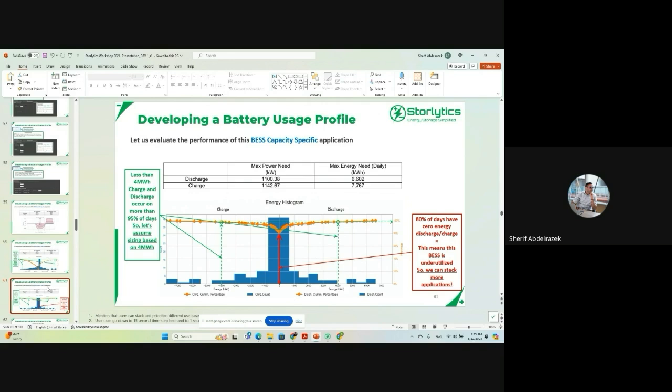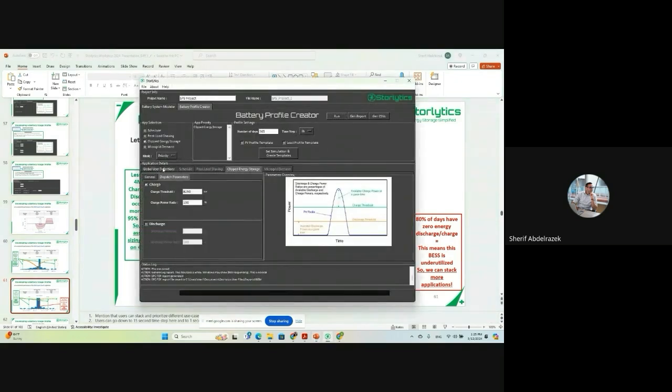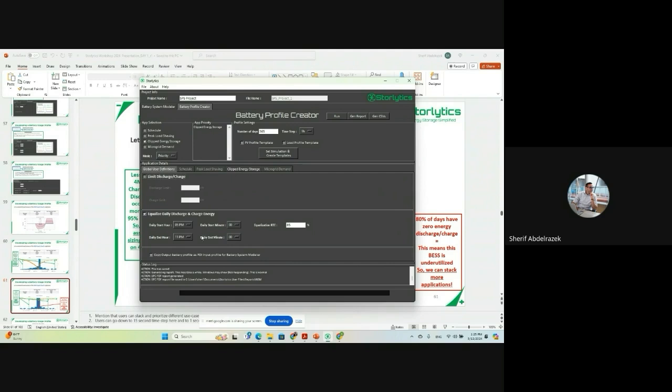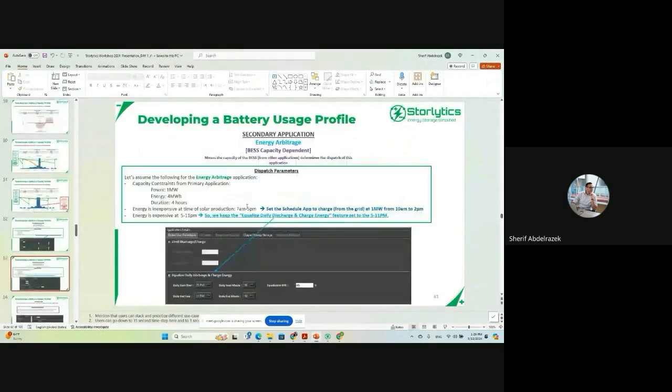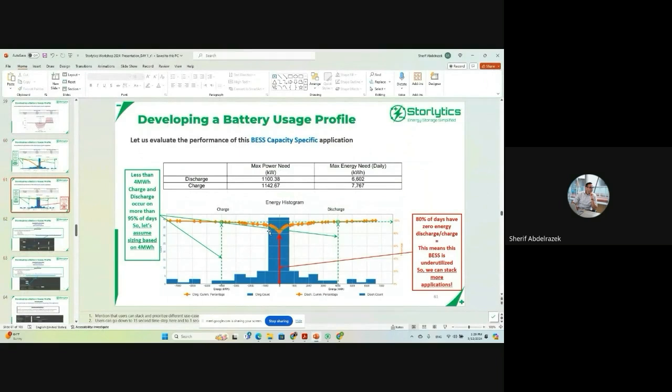For discharge, if discharging was calling for more power, I can maybe say, all right, how about I go back and increase the discharge period? That would reduce the amount of power I need. So as you're building your simulation and designing your project, you can prioritize different aspects based on your use case. What we can control for this project is discharge, but charging is based on solar output. So if I were designing this, I would give more weight to the charge piece for sizing in particular.